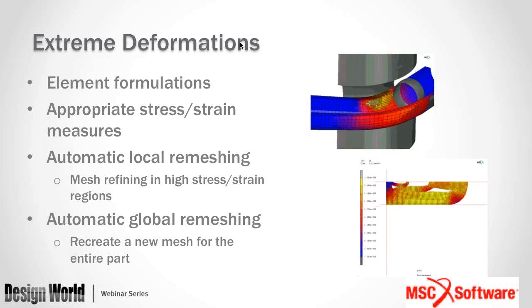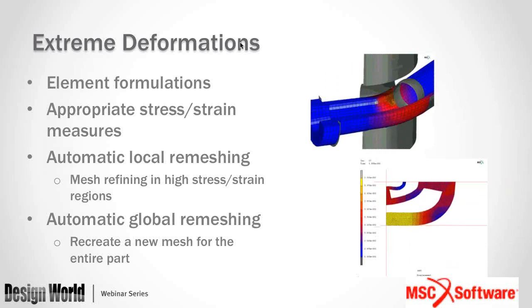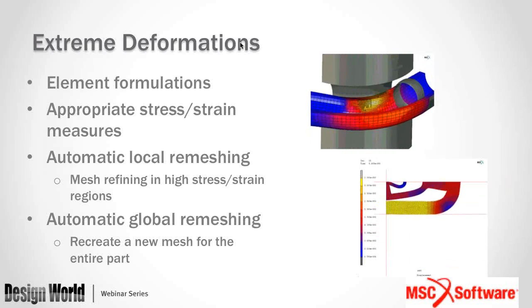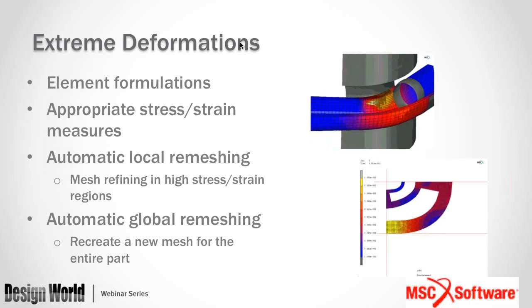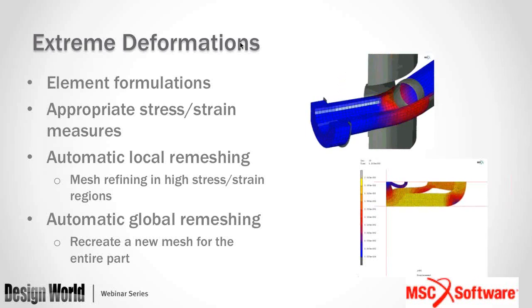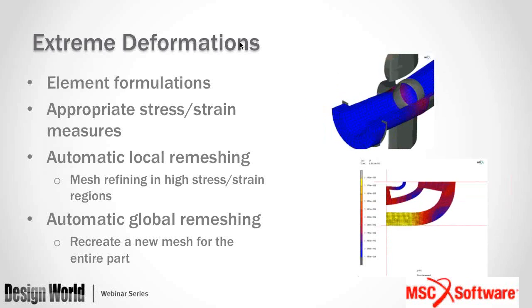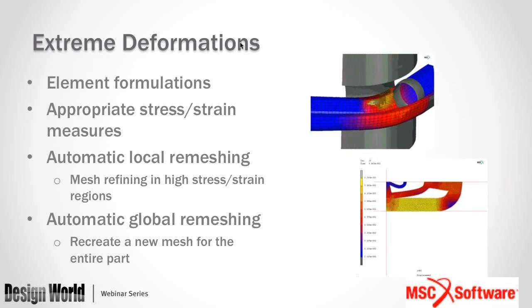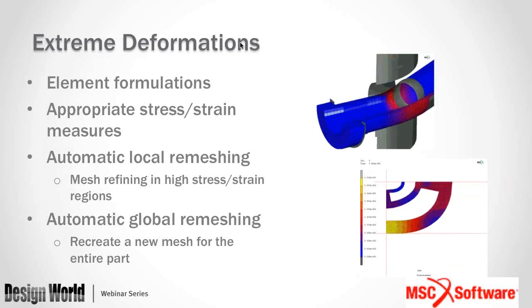So the software is refining the mesh locally, and you can get better stress and strain gradients wherever there are higher gradients in the structure without user intervention.